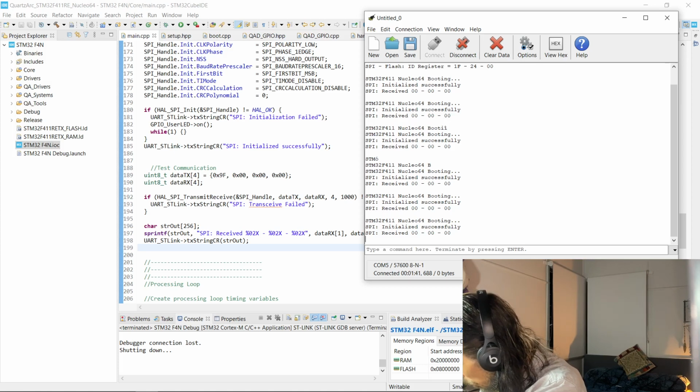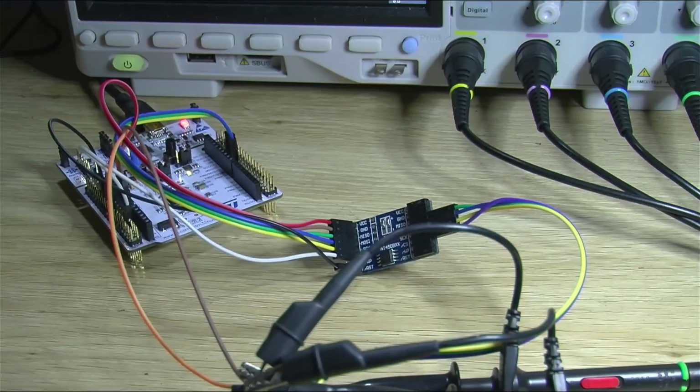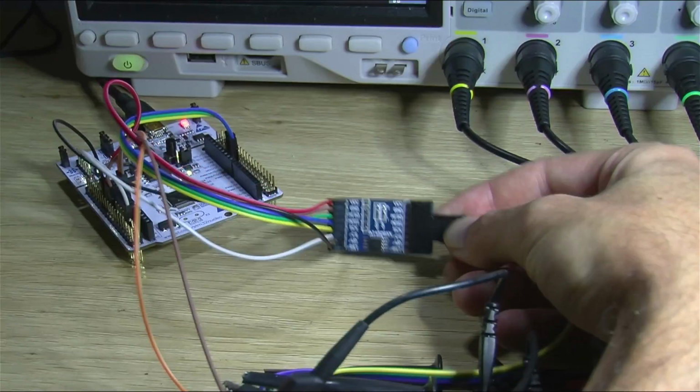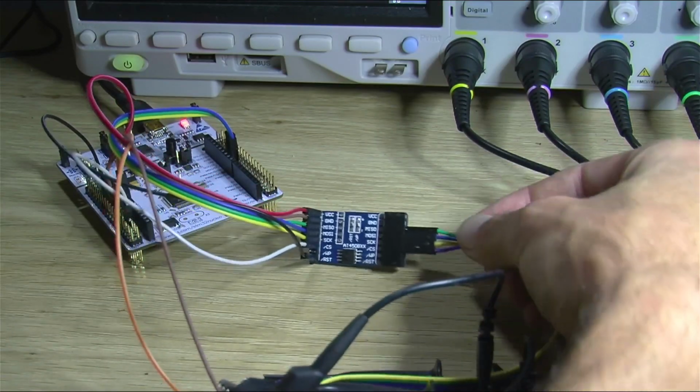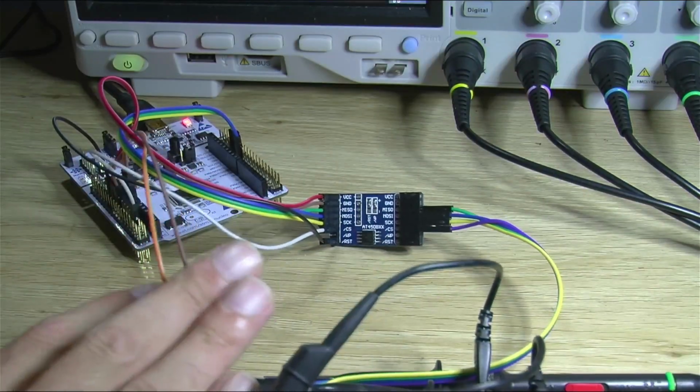Thankfully, it's just about ready to go, so connect that one up like so. Now let's jump over to this camera. We can see, thankfully, there is a pass through for the pins on this board, so basically just hook the scope up to those pins there. And then we've got a couple of ground connections just so that the scope can actually get a ground reference as well.